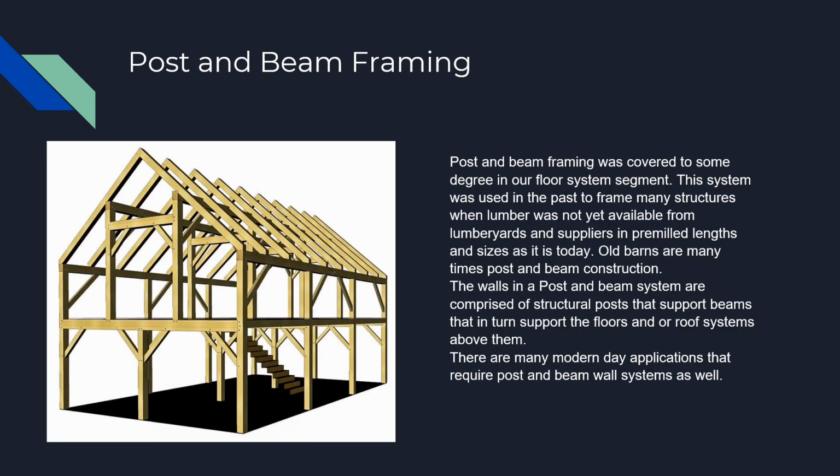Post and beam framing was covered to some degree in our floor system segment. This system was used in the past to frame many structures when lumber was not yet available from lumberyards and suppliers in pre-milled lengths and sizes as it is today. Old barns are many times post and beam construction. The walls in a post and beam system are comprised of structural posts that support beams that in turn support the floors and/or roof systems above them.